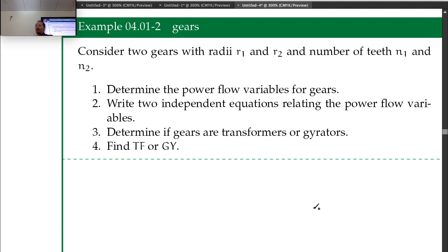So for instance, you're going to run a motor at like 1,000 RPM. You don't necessarily want your load to be spinning at 1,000 RPM. And also, you probably want more torque out of it than you care about the speed. A lot of times the speed is not what you want. So this gearing helps us do that. That's one of the things that gears are used for, and a lot of things use that concept. You're trading off torque and speed.